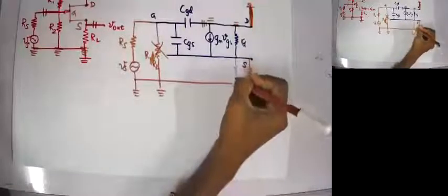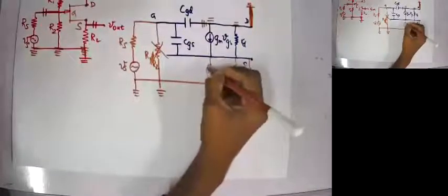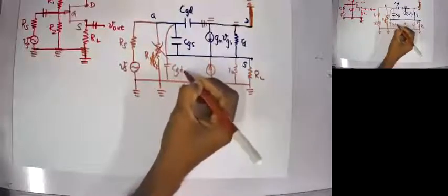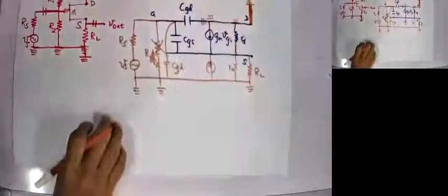Am I right? So now I am going to bring RD, VGS, and then this CGD here, right? So this RD will be somewhere here, and then this GM into VGS, but the direction will change from bottom to top when I am just simply folding upside down. And if I bring this ground here, so I have my CGD here, and then simply this will be straightened. So this will be my VGS, and that becomes a cross input and output, right?